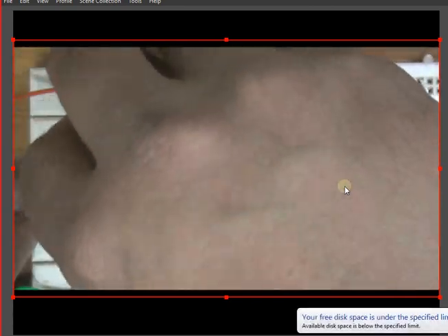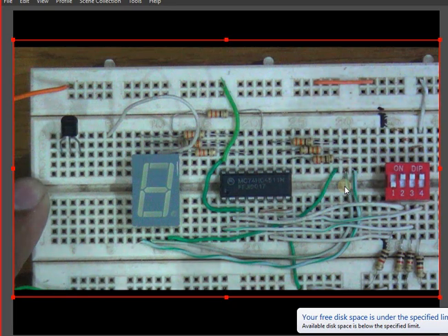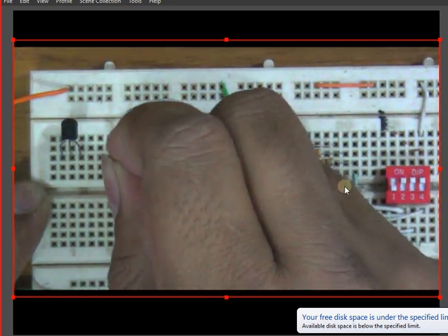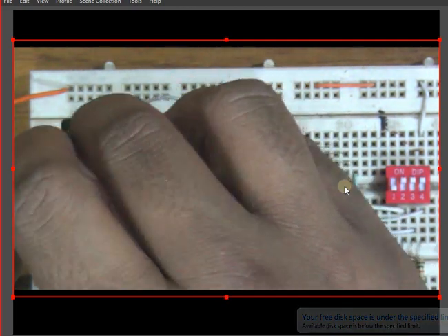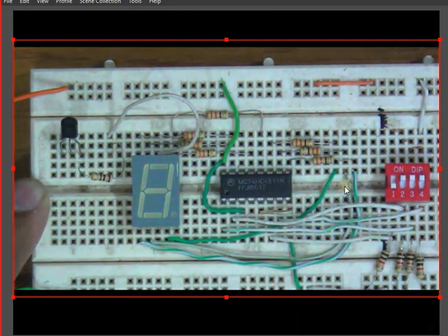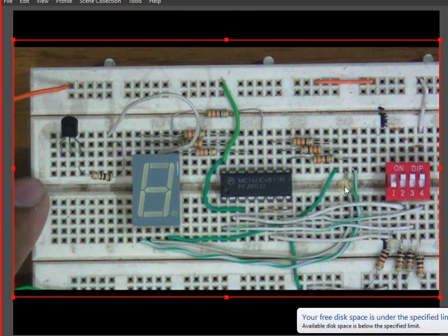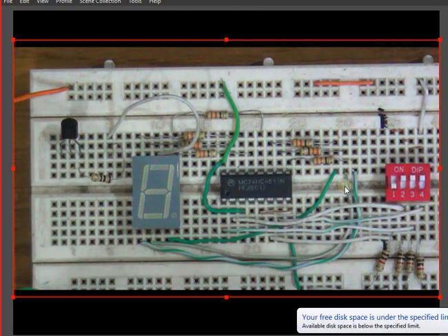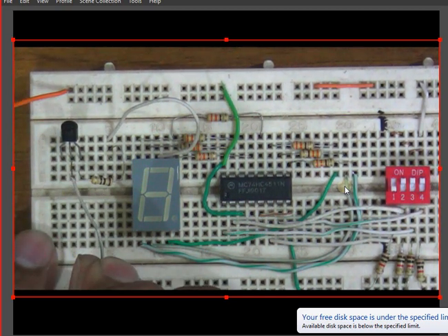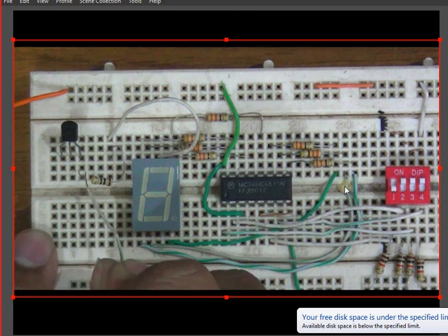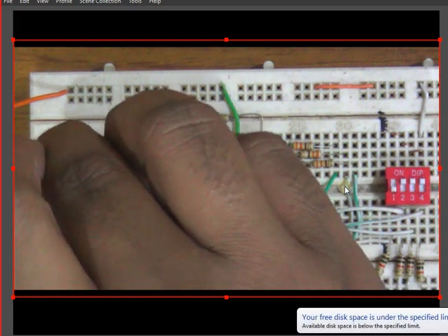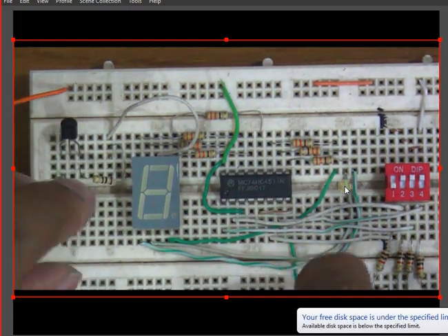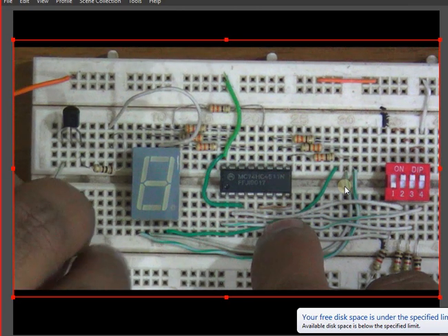So this is that common cathode point, and now from that common cathode point, I'm just going to take it a very even approach. So this is my resistor. I have used a 10 ohm, you can use a 33 ohm yourself. And then from the emitter, what was emitter? This one was E, second pin was B, the third pin was C. I have connected the collector on this pin, and now I am going to connect the emitter, that is the first pin, and I am going to take it towards the ground pin.